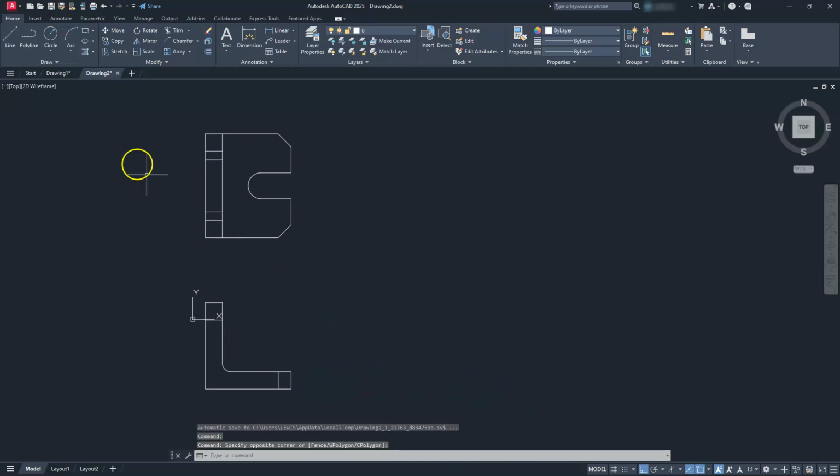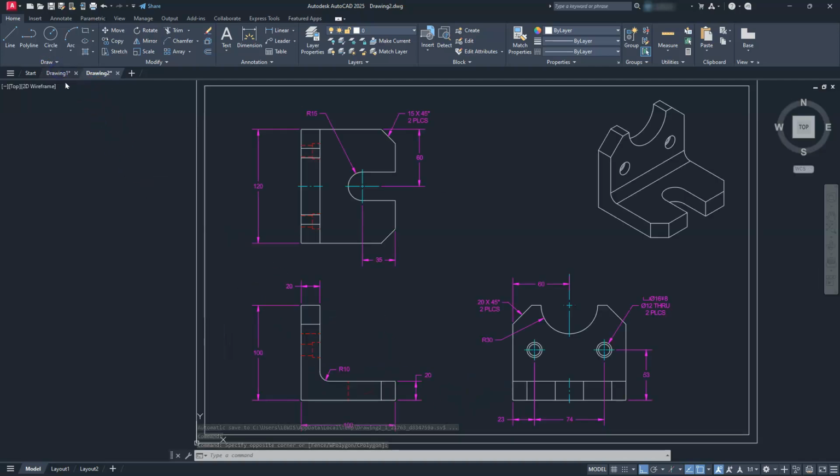Now we can go back and start figuring out how far this is going to be. So this bottom line, remember that this edge here is actually representing this edge here. So I'm going to create a rectangle, just like we did here at the top. The number here, in this case, the X direction is going to be 120, and the height of this will be set to 100.